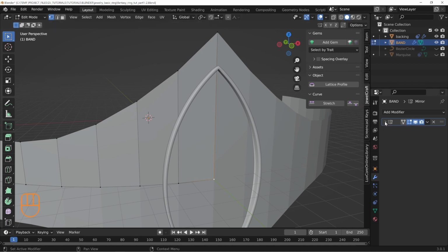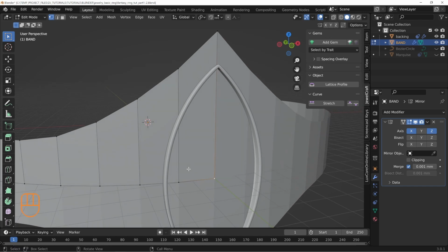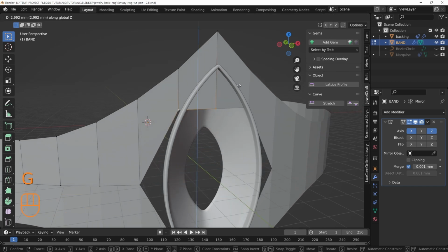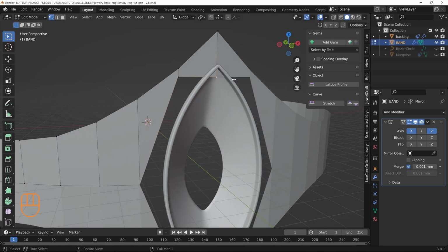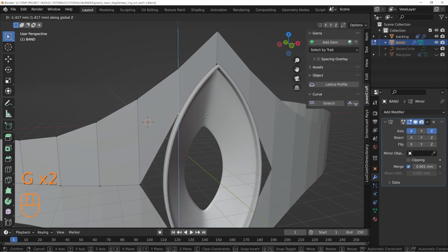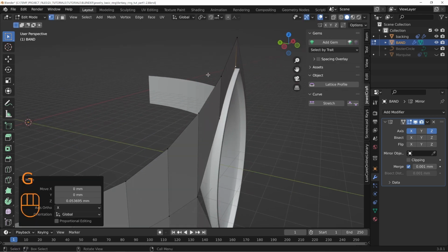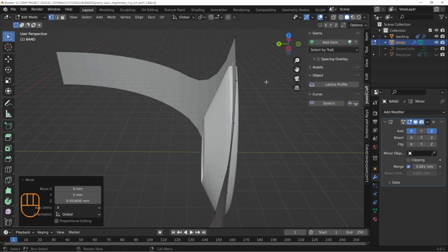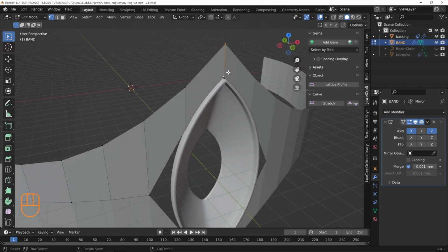So what we'll do here is we'll actually remove the clipping right there. So turn the clipping off, and that will allow us free reign to just pull these sections around and do what we want with it. Make sure that you're locking this on the Z when you do it. You don't want to accidentally move it in a direction that's not in a circular method.